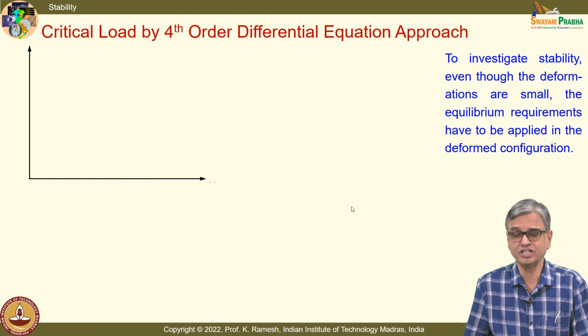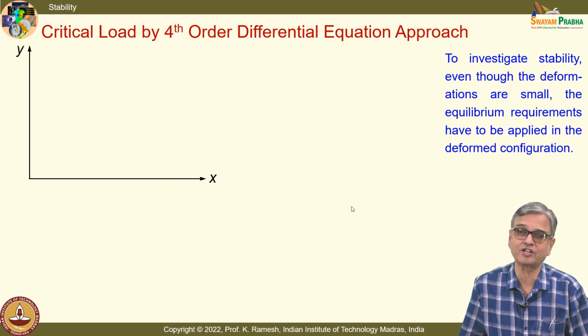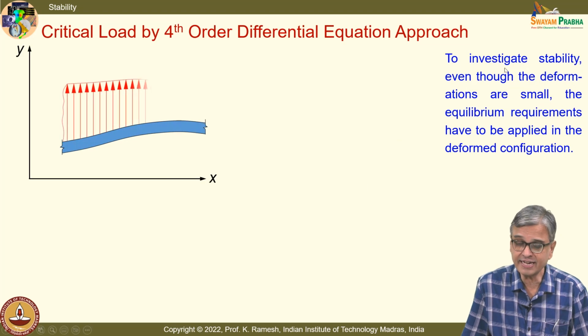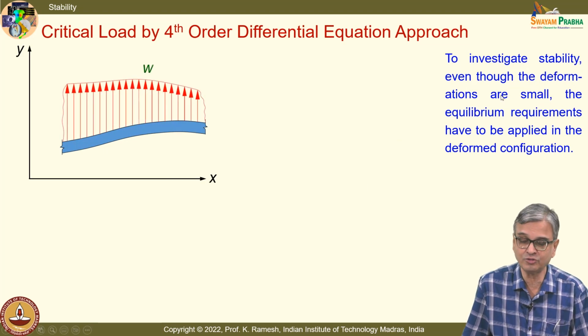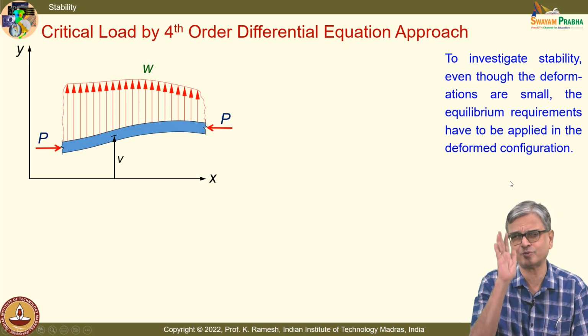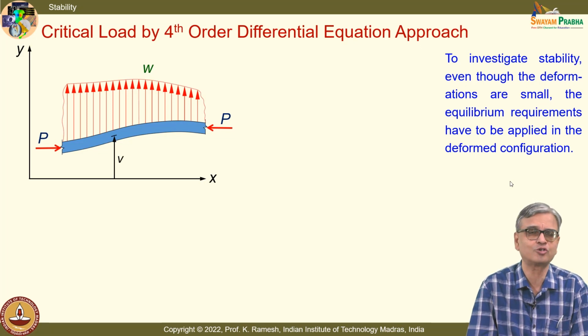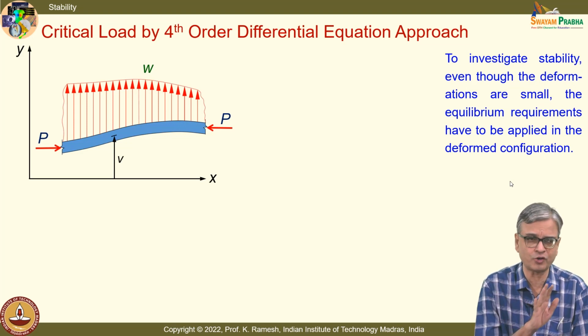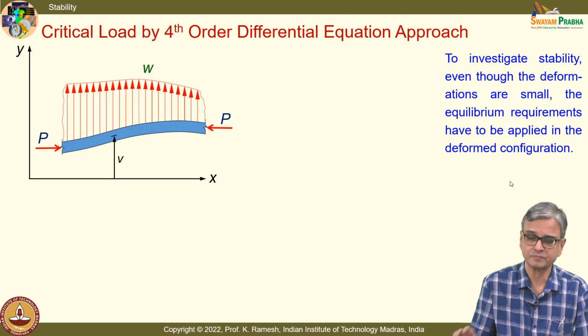And in this chapter, we also make a conscious decision to investigate stability. Even though the deformations are small, the equilibrium requirements have to be applied in the deformed configuration. This I alerted you even a long time back. In this course, because the deformations are small, we will work with the undeformed configuration for all the mathematics. We make a departure when we want to investigate stability.